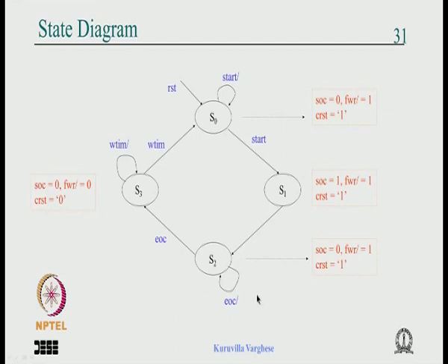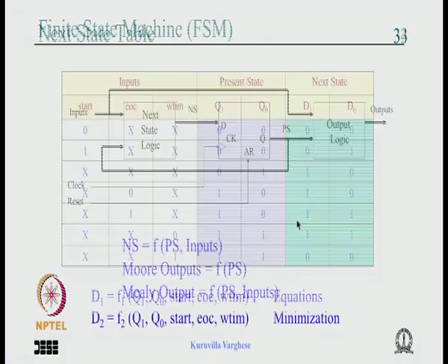And that was the control algorithm, and we have written a state diagram and the exactly similar thing. So there are inputs, transitions, states and the output, and we have decided to use D flip flops for state binary encoding, so 00, 01, 10, 11. From the state input transition you can work out the next state table, and from the state output you can work out the output table. So we have done that.